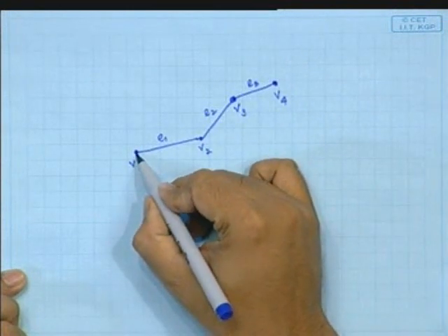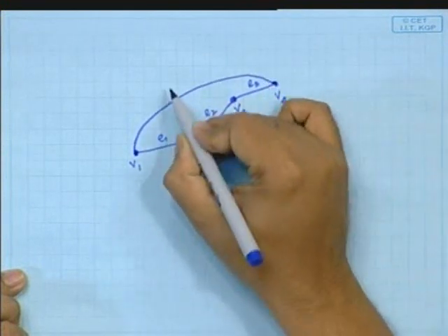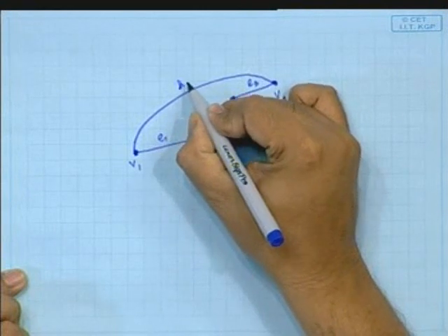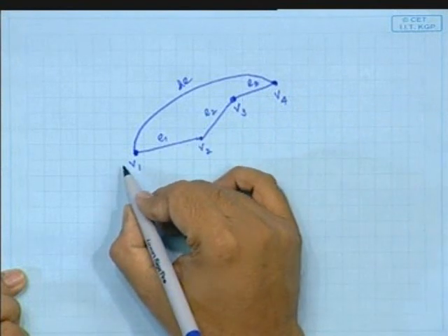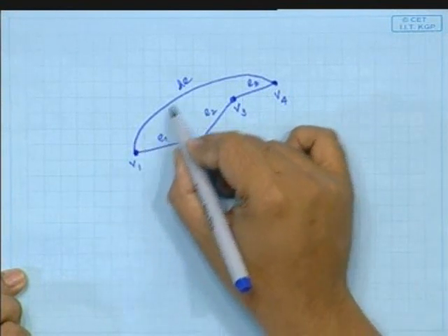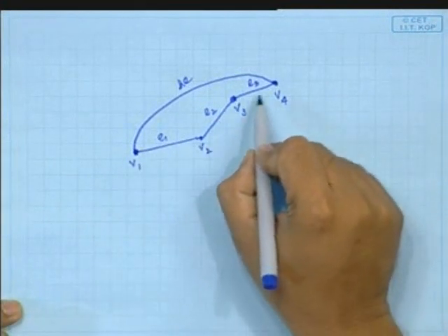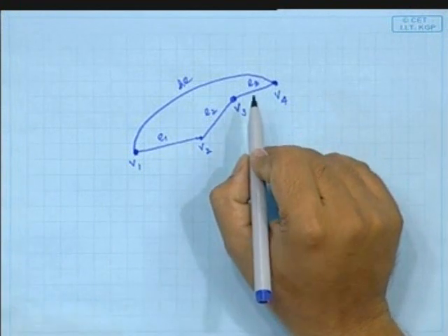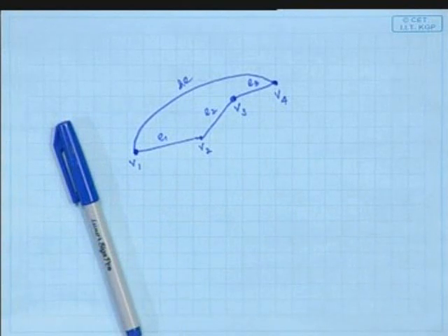So if I represent just the connection between V1 and V4, this is, say, the hyperedge. It is actually this wire that is represented, but in my partitioning problem I represent this hyperedge. Got it? So this hyperedge is actually a subset of the vertices. This is a hypergraph, where the vertices are the vertices of the graph and the edges are subsets of the vertices itself, right. Okay.